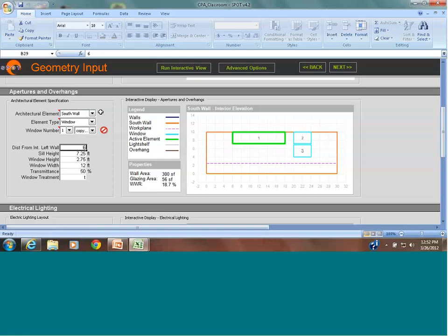Let's say we have a glazing that is 60% visible light transmittance, and if you put a perforated metal panel in front of it that's 50% open, then we could simulate this as if the glazing transmittance is 30%, or 50% or 60%, just to understand how it will work.